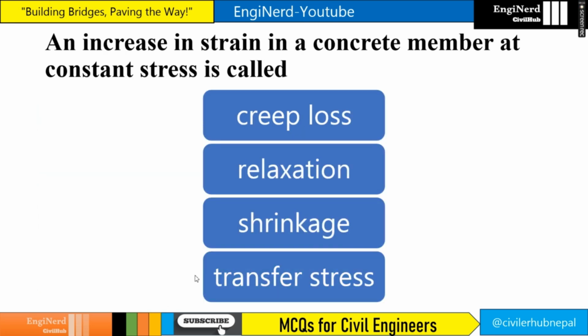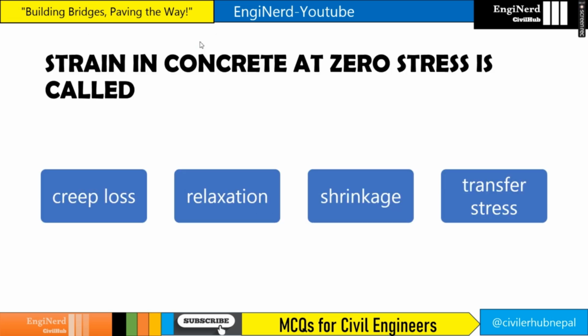Next, an increase in strain in a concrete member at constant stress is called what? If the stress is constant and the strain is increasing, then it is called creep, a time-dependent loss, right? Next, strain in concrete at zero stress. If the stress is zero, it is shrinkage, right? Even if the stress is zero, there can be strain in concrete caused by shrinkage.